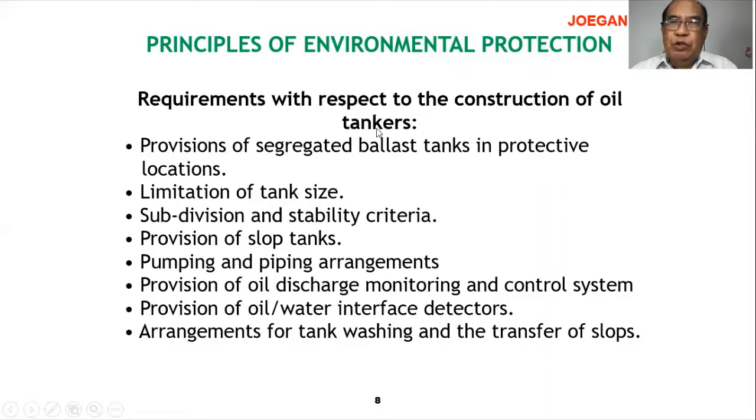Requirements with respect to the construction of oil tankers. Provisions of segregated ballast tanks in protective locations. Limitations of tank size. Subdivision stability criteria. Provisions of slop tanks. Pumping and piping arrangements. Provisions of oil discharge and control system. Provisions of oil-water interface detectors, arrangement of tanks, washing.